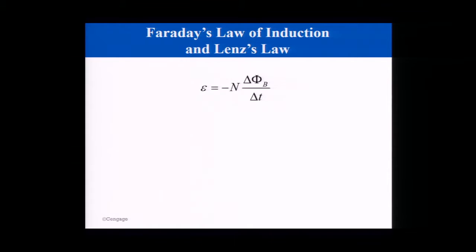And that's going to become really important when I start building my circuits, because we saw with a capacitor, we had a time lag as the capacitor filled, right? We saw that it took a little while for it to fill. Resistors were instantaneous. We saw the effect on current. With a resistor, as soon as we hit the switch, we didn't see any deflection. It just was instantaneous.